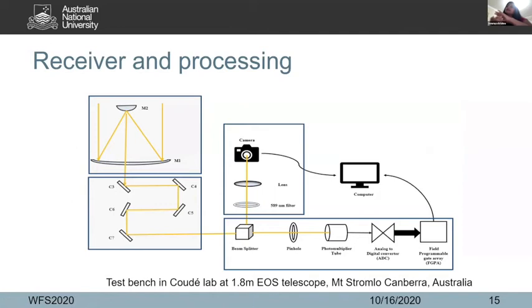In our case, that's the photon detector we're using, and we'll be using an ADC to get the output in terms of digits. And again, we'll be doing a cross correlation on an FPGA between the photon flux and the PRBS to get back the profile.